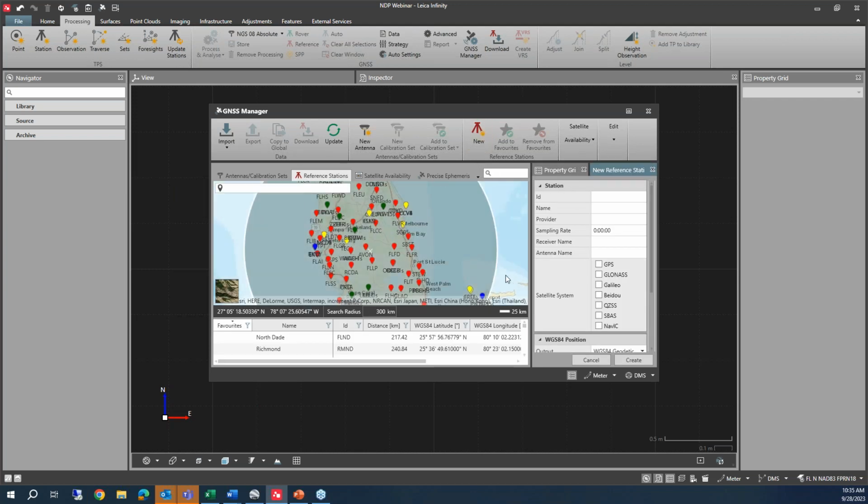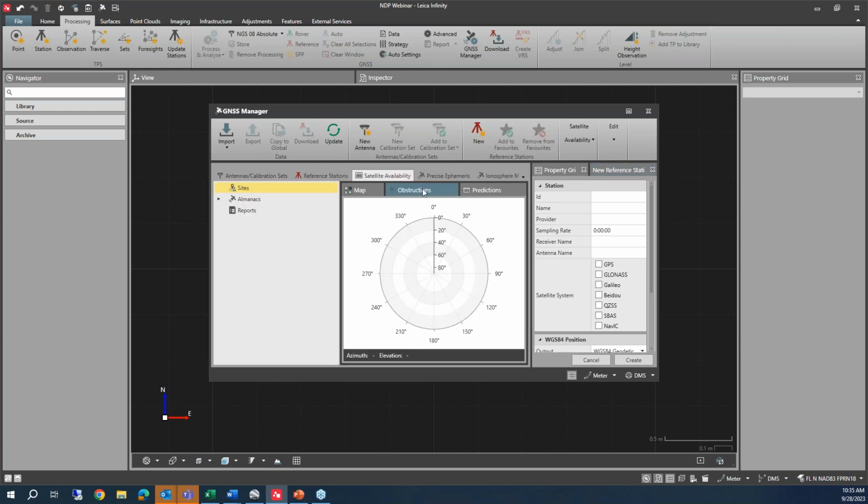Oh, I'm sorry, that's pulling up the reference stations. So we're going to create point number 5523C1001. It's going to receive all, you check until it receives all four constellations, because that's what we're doing on this. Give it a latitude and longitude. In this case, it's,